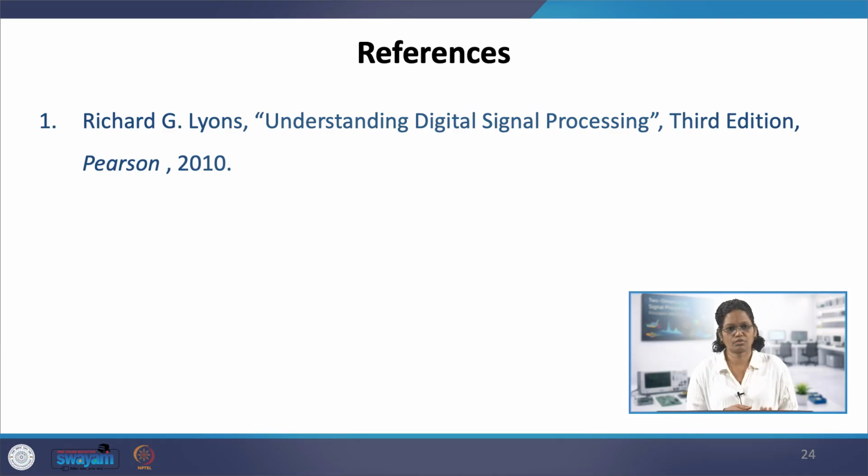1D FFTs are useful for doing the 2D FFT. Like 2D FFT is performed through the 1D FFTs. Like we did in the linear convolution of 2D, we have two 1D convolutions, row-wise convolution and column-wise convolution, if the impulse response is separable, that is, the second sequence is separable. Similarly here for 2D DFT computation, we did one example of 2D DFT direct computation, and looked at its computational complexity. To reduce the computational complexity, we can go for FFT.